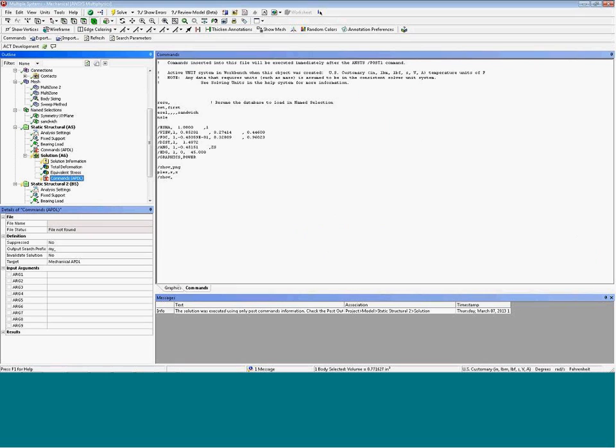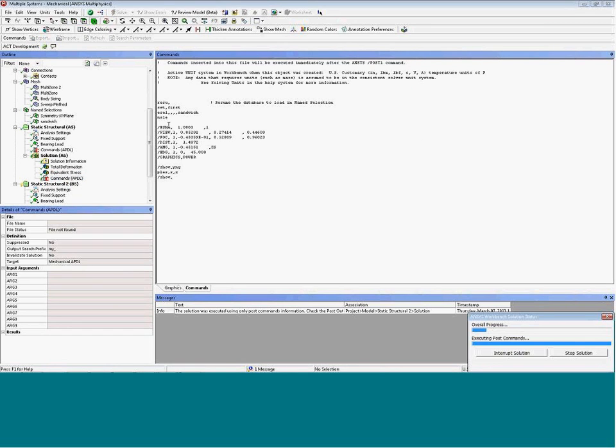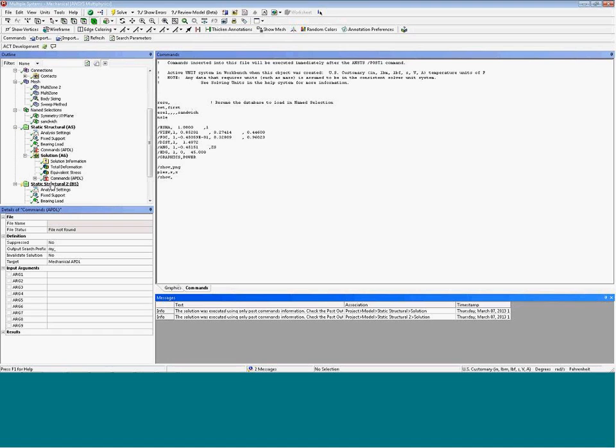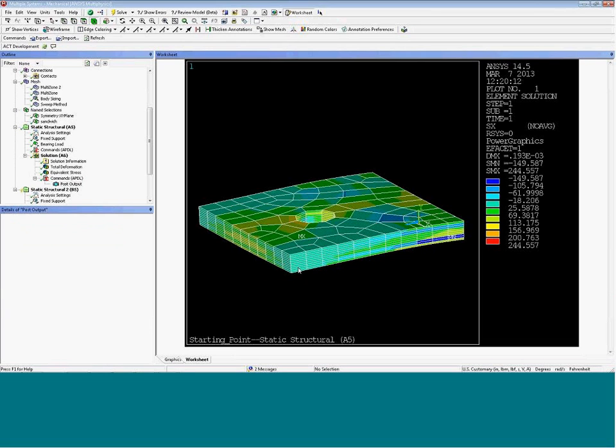body down here, and then I'm going to create a plot of that. So let me evaluate this. These are just some view settings, and then this is /show PNG. We'll take a picture, and it's a picture of the stress in the x direction for just those elements that I selected. You'll notice if you put in /show PNG, it'll put in a picture below the command block. It's the picture that we'd see in classic ANSYS, if you were to write a file, read the results in, and look at it in that GUI. So that picture shows up in here.